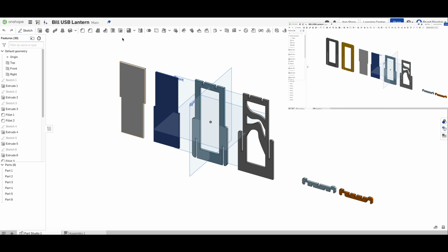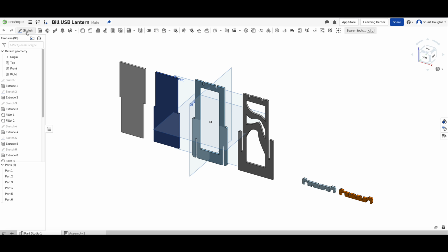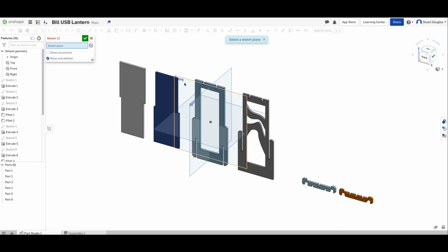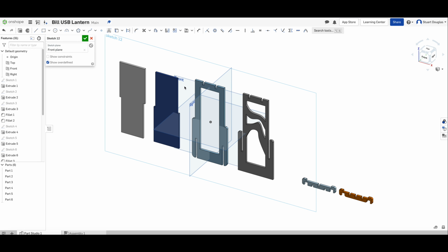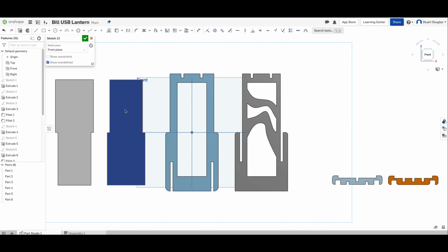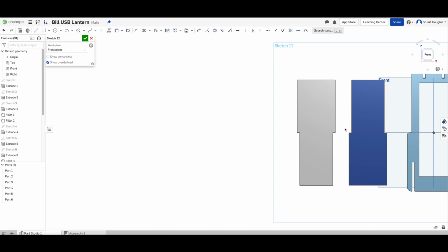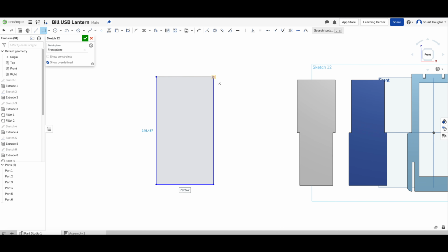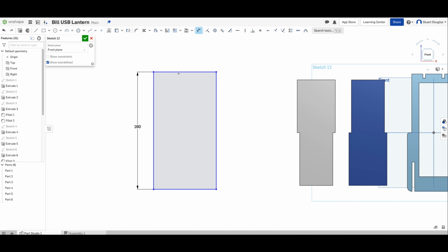Type A panels, I'm going to choose to model that on this side of my screen. So let's start off with a sketch on the front plane. Front plane's here. Let's pick front, hold the middle mouse wheel down, and let's slide it to one side. Choosing the rectangle tool, I'm going to do my first one just over here. Okay, like so. And I'm going to change the dimensions, as we have in our previous work, to be 160